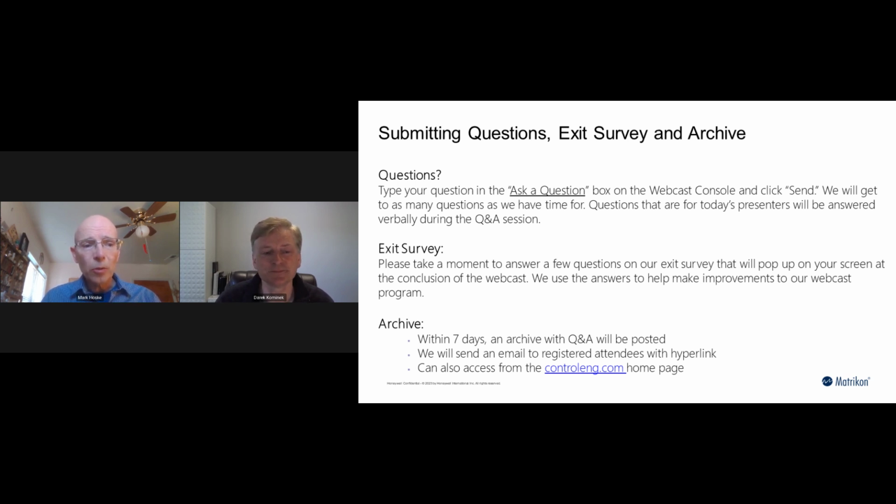Good. Does using a unified OT data layer architecture replace the need for a historian? Depends what you're trying to do. If you're primarily using a historian just to access your real-time data, or you're working with the sources, maybe. But I think the point more so is to enable broader, secure, uniform access. If you've already got an application where you're happy with using whatever comes off that historian, it is not meant as a replacement. Whether you choose to do something else, or you're moving to cloud or whatever else, that's up to you. But no, it's not a replacement. It's at least an augmentation of how you access the data, or the historian just fits into the UODL as well. It's just a component in your system.